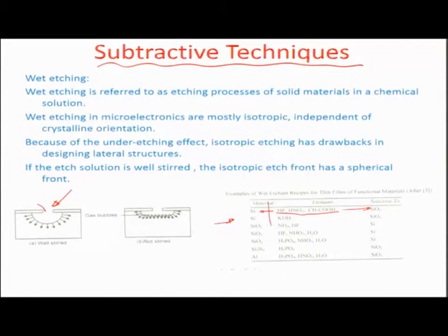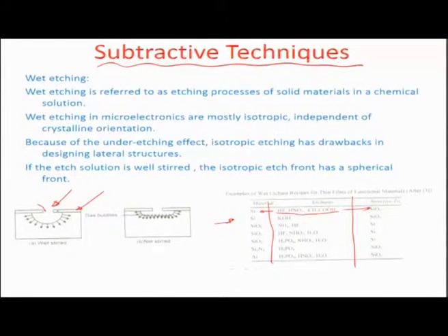And similarly, in all these different materials, you can have a common material and a selective material. So, now the advantage is that whenever there is a selective material, you can use it to block the etching process from carrying forward any more, and that creates a very big advantage in terms of microstructuring, because let us look at this particular example here, where this material is an etch selective layer to the particular chemical that is being used.